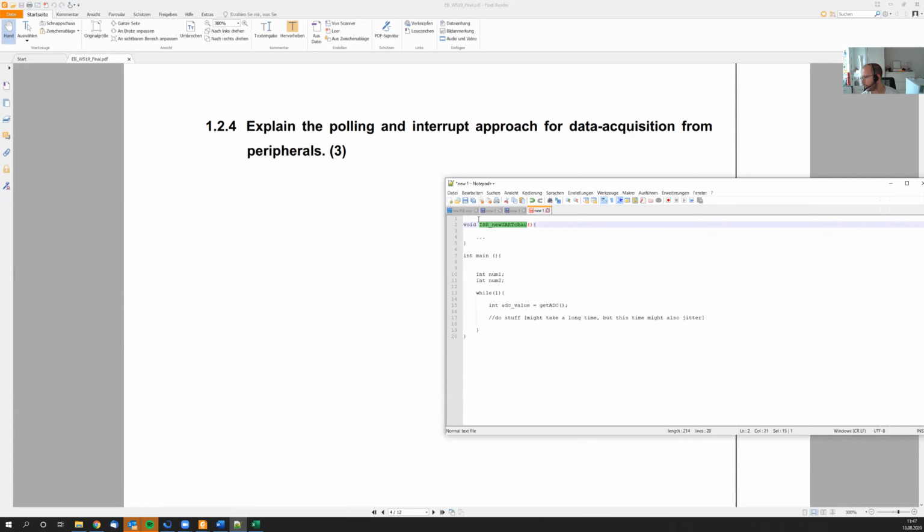Of course, now this interrupting the CPU might cause other problems. Especially, for example, there are even attack scenarios called interrupt flood. Basically, you do something so that the ISR gets called all the time, so that your main program doesn't have time to do anything because it spends all the time in the ISR. So this whole timing can become critical with interrupts.